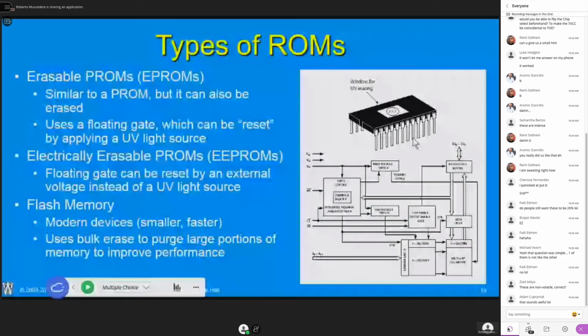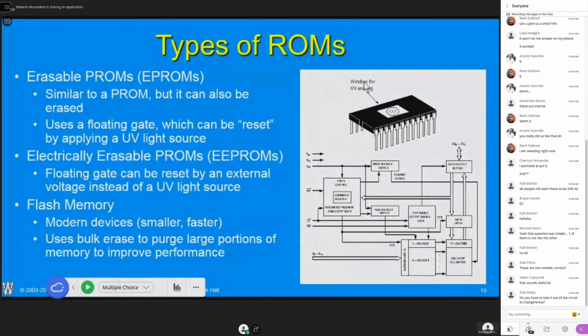Okay. Now the next stage is, well, what if I don't want to wait? Yes, I do have to remove the circuit, so these would be socketed. Now they look just like this. They're DIP packages, right? DIP packages fit into breadboards, those types of things. So they're easily removed, and we can get better sockets. There are different types of sockets out there, better quality sockets. The best quality you may have heard of is called a ZIF, zero insertion force socket.